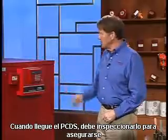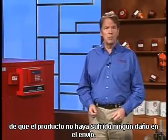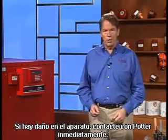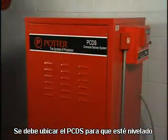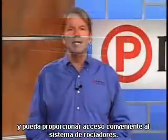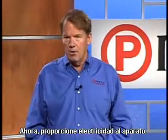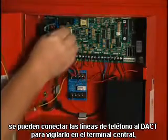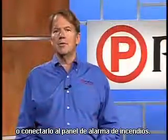When the PCDS arrives, you'll want to inspect it to make sure no damage occurred during shipping. If you find the unit has been damaged, contact Potter right away. The PCDS should be placed in a location that is level and provides convenient access to the sprinkler system. Next, provide power to the unit. Once the wiring is connected, you can connect the phone lines to the DACT for central station monitoring or connect to the fire alarm panel.